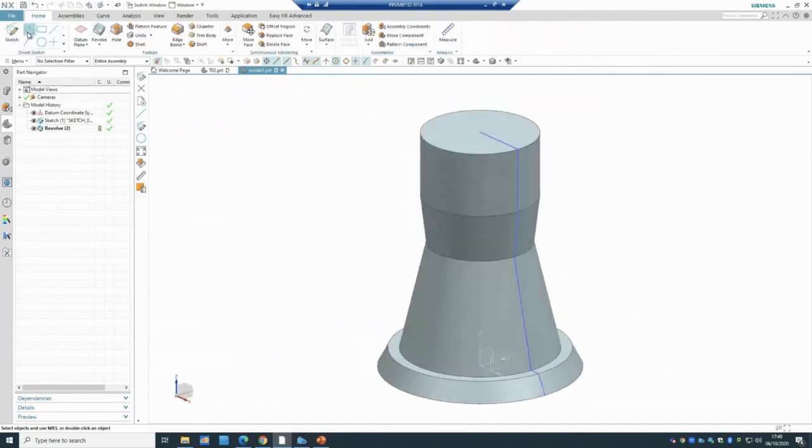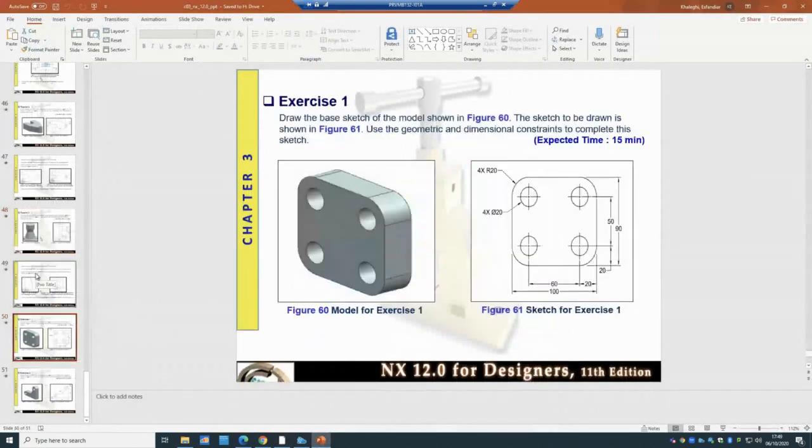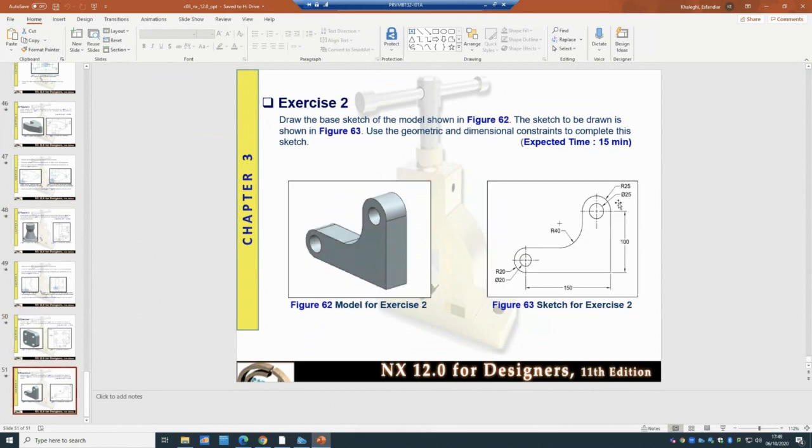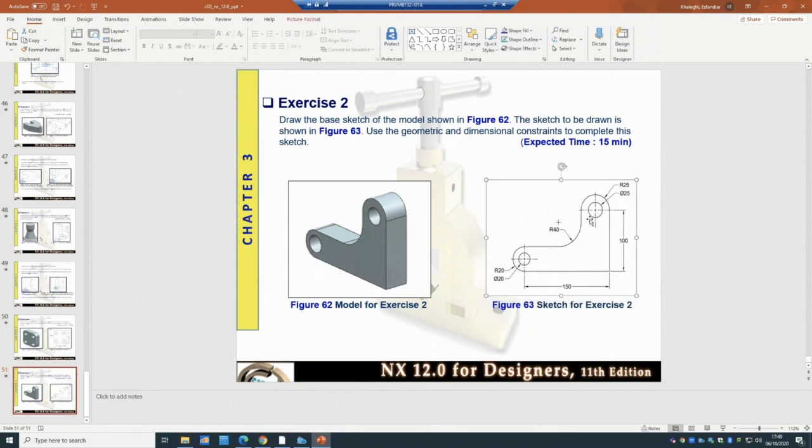Great. So that was it for the 2-day session. I've uploaded these for you, and I put 2 more exercises there. This one is quite simple. You can see it's the normal cubic shape, then you have the circles with these dimensions. Just do a normal extrude. You can do this other one as well, which is a line, and the best way I think is a full circle, tangent line, tangent line, tangent line, tangent line, and then you do a fillet there, and here and here is fine, and then you just put 2 circles and extrude. These are quite simple. That's why the time is 15.